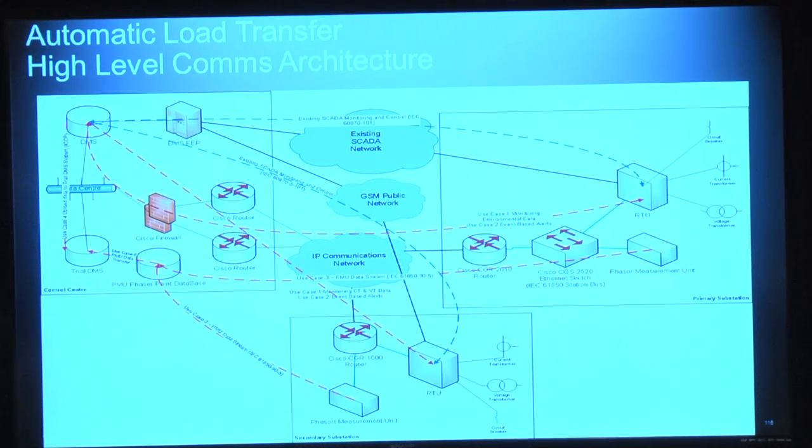Again, this was just a maturity thing and a confidence thing for Western Power. Once they had the confidence on the IP comms network pathway, those legacy, if I call it that way, networks, the UHF and GSM networks, were able to be disconnected. But at the time of the project, they were maintained and in place for, I guess, duplication of data effectively